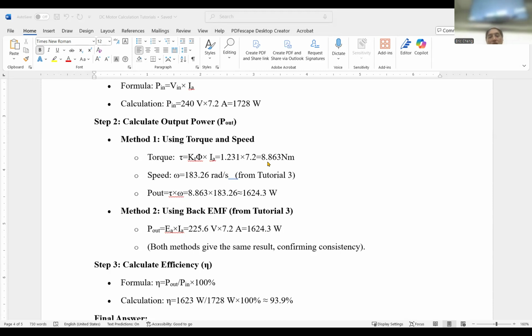So let's look into the dynamic braking. For the braking, let's see how it looks. A DC motor with armature resistance 0.5, and then we are now doing dynamic braking. That means we remove the DC source and put a resistor there for the dynamic braking. So when this motor is running, the back EMF is equal to 100 volt.